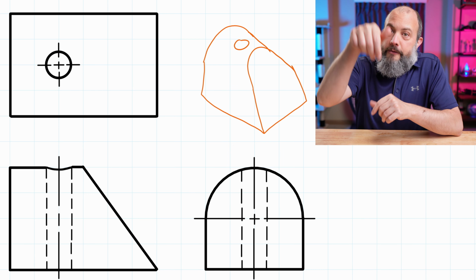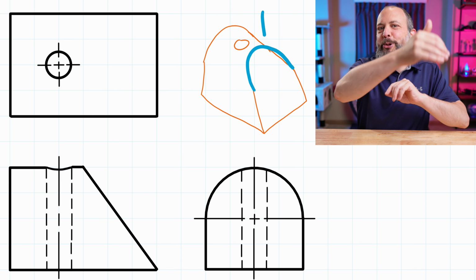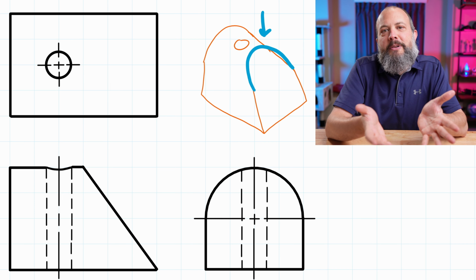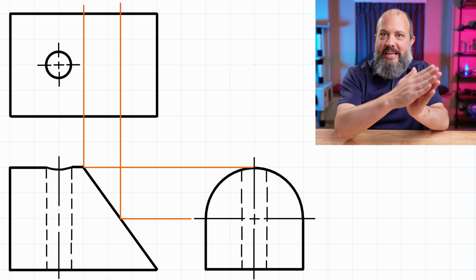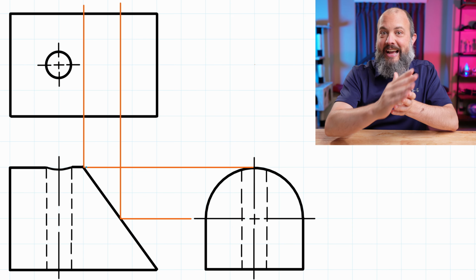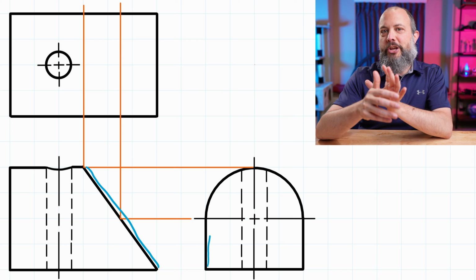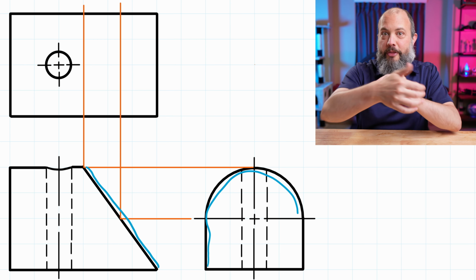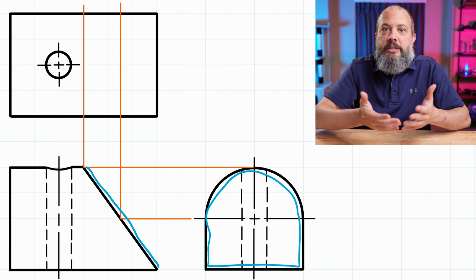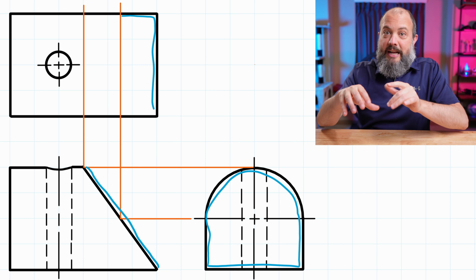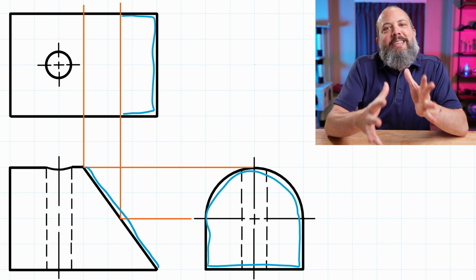So now imagine you are looking from the top down at this shape. From the top view, you would actually see this rounded blue line. That would all be visible from the top. The best way to think about this when it comes to actually drawing it is that an angled surface looks like an edge on one view. So on the front view, that diagonal line that you see looks like a face on the other 2 views. The exact same face that we see on the right view, rectangular with a round top, you'll see that exact same shape on the top view, just rotated 90 degrees because of the miter line. So the bottom of this blue outline is already drawn, it's just the right side of the top view. But the round surface, that's the missing line that I have to add.